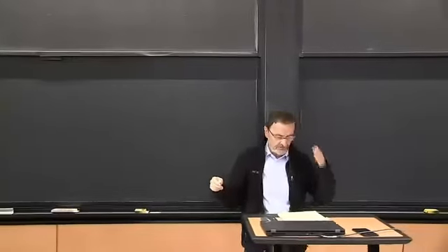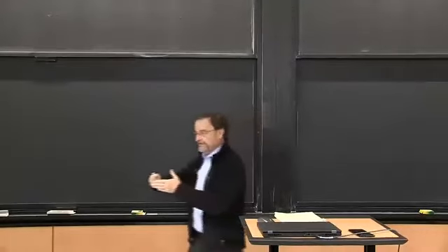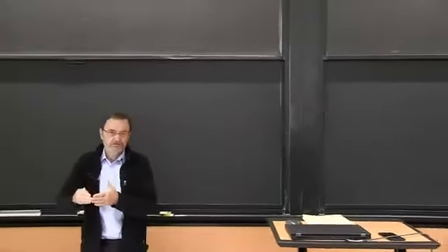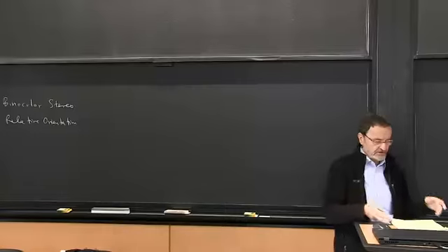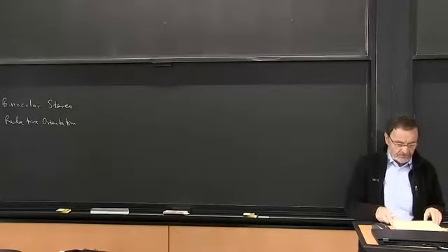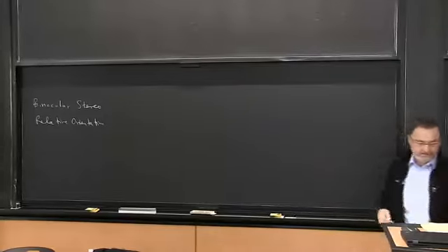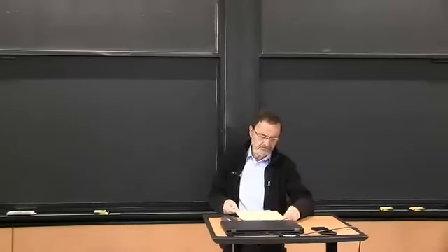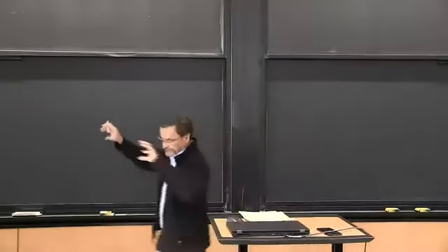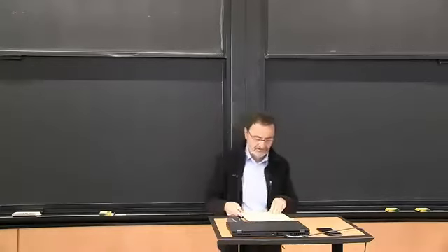And now you do that for the left camera, and you do that for the right camera. You have two rays, and ideally they'll intersect, and that gives you the 3D position of the thing you're looking at. So that's the easy part. In order to do that, you need to know the geometric relationships between the cameras, and that's what relative orientation is about. And so that's something that you would do ahead of time before you install this thing in your car and use it for autonomous vehicle purposes.